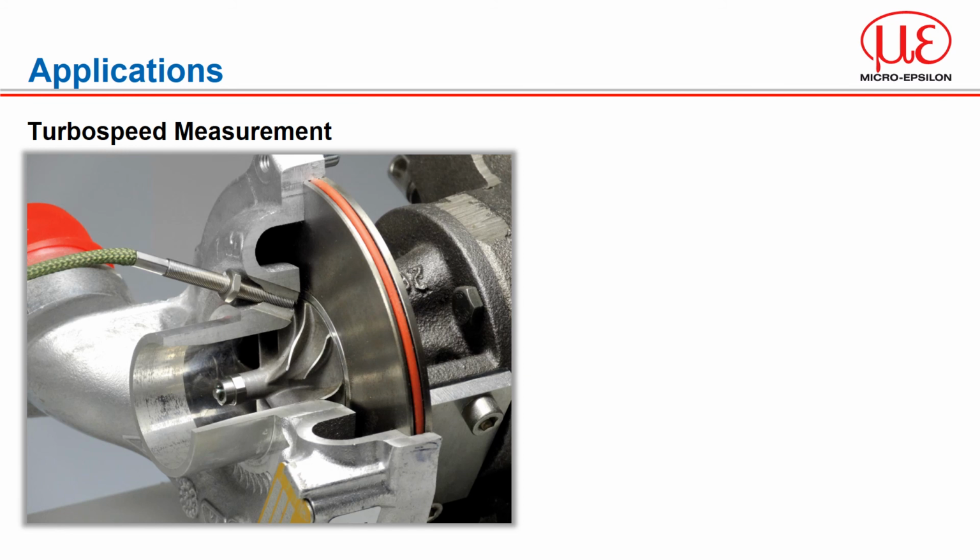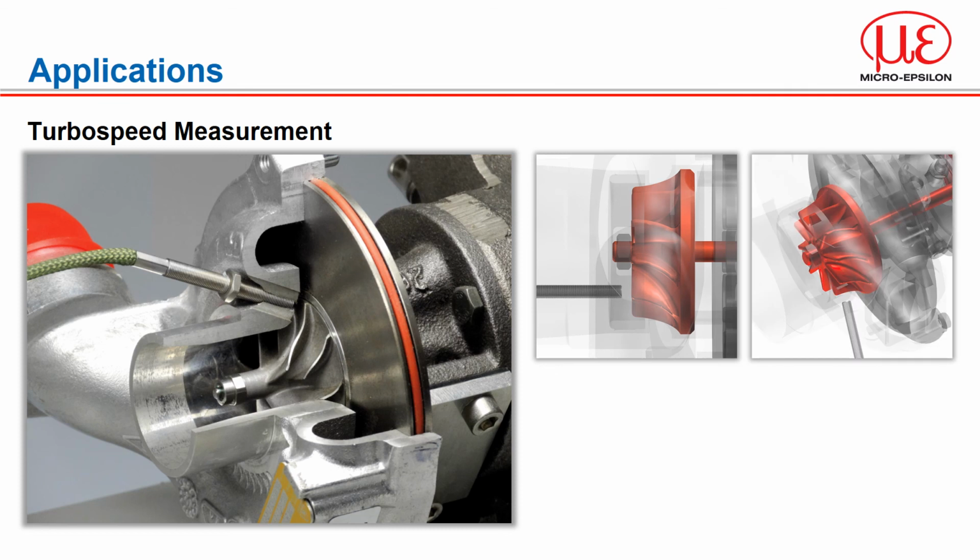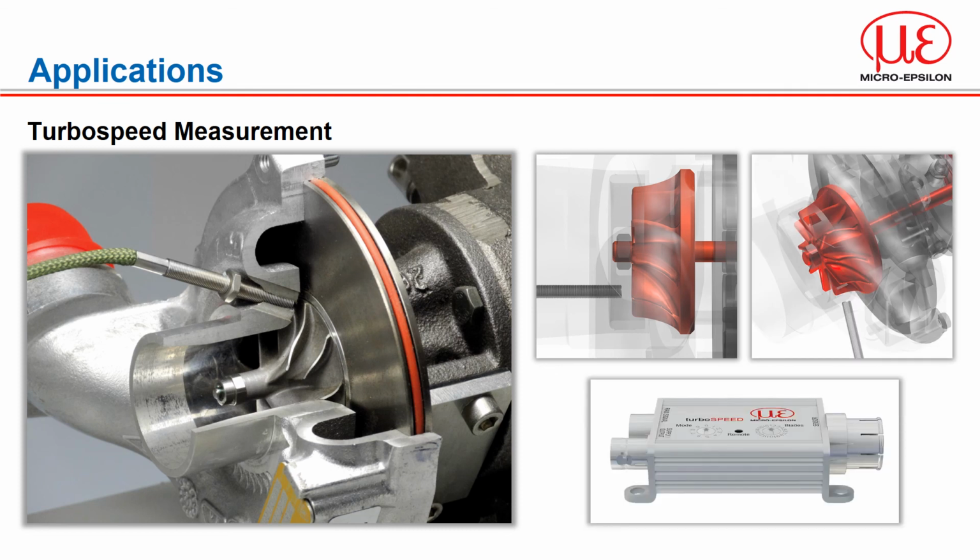Another application that utilises eddy current sensors is that of turbo speed measurement. The spin-up of the turbo is essential to reducing the lag between when you apply the accelerator and the expected power kick the turbo delivers. Eddy current sensors are mounted directly in the compressor housing of the turbo and give pulse feedback from the fins or blades of the turbo as they pass. The fast response is key to this measurement, with multiple blades passing every rotation. The system is capable of measuring speeds up to 400,000 RPM.